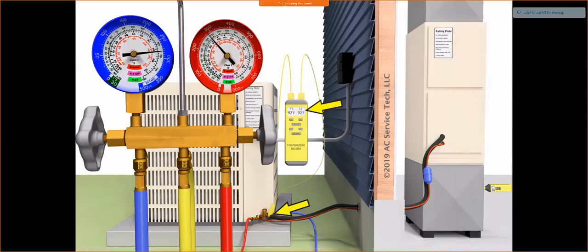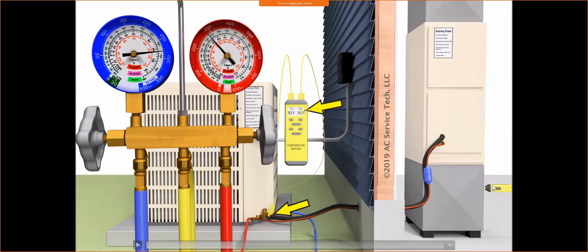The other thing too is if you were to take this thermal probe and actually attach it right outside the evaporator, you're going to get a more precise reading, all right, because we're taking the temperature exactly as it's coming out from doing the work. We may absorb another degree or two as it travels down through the insulated line, but from a convenience standpoint, a lot of times we're just going to be grabbing the temperature right outside of the vapor line.